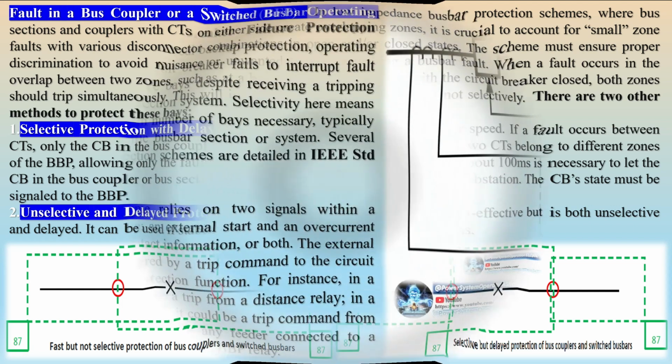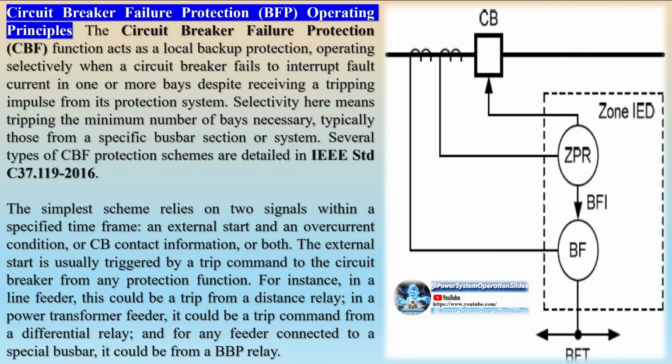Mesh busbar scheme. This scheme features a fully selective protection system with busbar differential protection at each corner. A fault at any corner trips the two associated breakers and initiates inter-tripping to open circuit breakers at opposite ends. Each busbar is considered individually, and a single busbar scheme is applied to each.